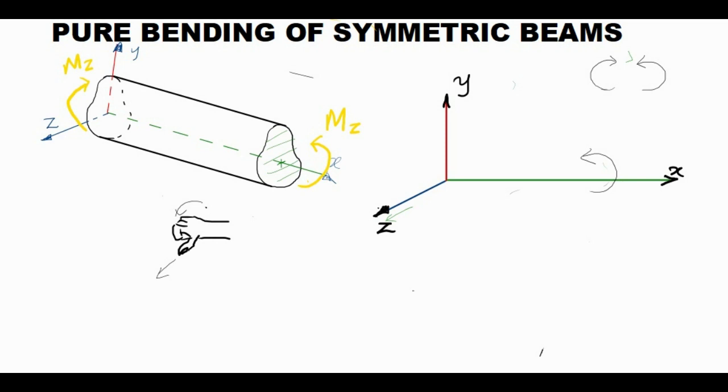But in the case of bending moment, even though the couple is negative, the bending moment is positive. Why? This moment is applied on a negative face. If we take the normal here, that will be in negative x direction, so this is positive. On both sides we have positive bending moments. Now we will consider the bending of this beam.